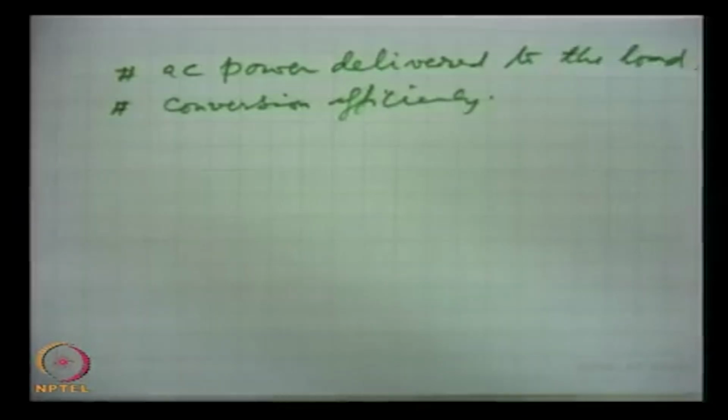And now, how are the devices and circuits of power amplifiers different from small signal ones? When we say that the amplifier is supposed to deliver large power, that means the device, the transistor, should be capable of handling that much power. So, in general, power transistors have a larger surface area.